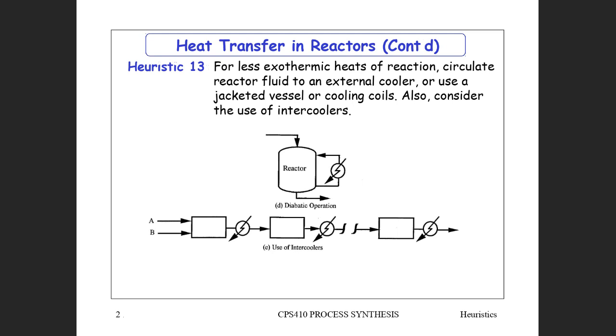Similarly, for this one, you can set up a laboratory experiment where you raise the temperature exactly according to an adiabatic reactor. So not even in the laboratory, on a pilot scale, for instance, you can have these sections where the temperature rises throughout the reactor adiabatically. And therefore your laboratory or pilot plant results are going to mimic the large reactor quite well.